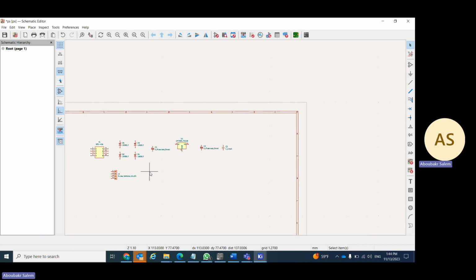So if you have 2 contacts at a distance of 1 centimeter, and you apply 1000 volt, this is going to flow current in air. Okay, so this is going to polarize the air and flow current between the 2 contacts. So you have to keep a certain distance according to the voltage magnitude you have.